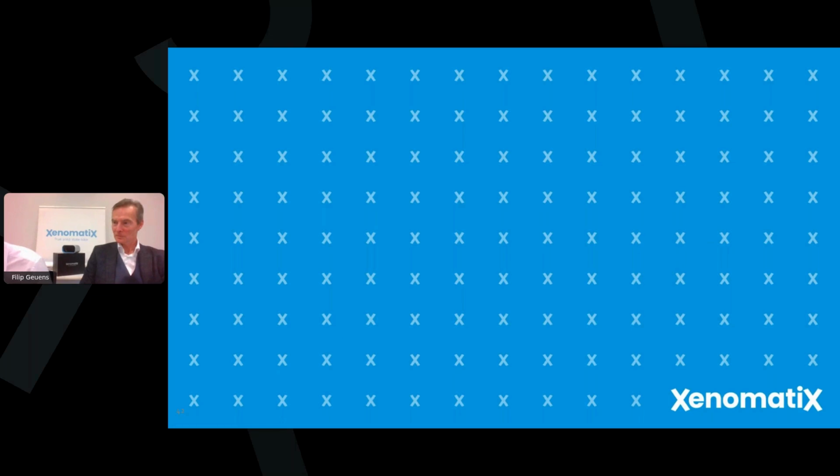I have here also one. How many LiDAR sensors do I need to create sensor fusion with a 360 panoramic camera? I would say at least 6, maybe 7, because the field of view is just below 60 degrees. But you have to consider this LiDAR as the equivalent of a standard camera. It's a unidirectional LiDAR.